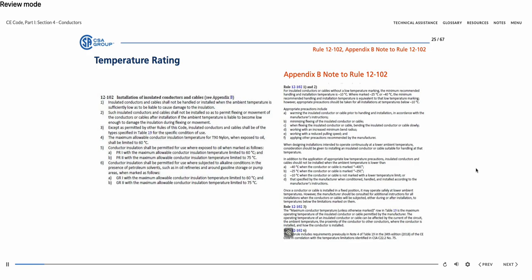The low temperature marking on conductors indicates compliance with a test at that temperature, as specified in the product standard, but does not guarantee safe installation at that temperature. Take care when installing cables at low temperature, which is below -10 degrees Celsius. You should precondition the cable at higher temperatures prior to installation and avoid mechanical shock from dropping the cable. You should not unreel the cable too quickly or bend it sharply or quickly. Consider future movement of the conductor at low temperatures after installation.